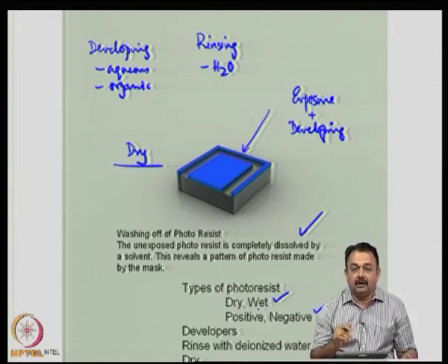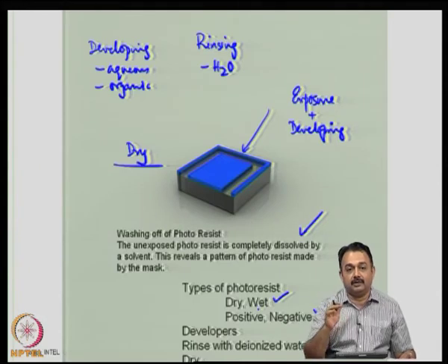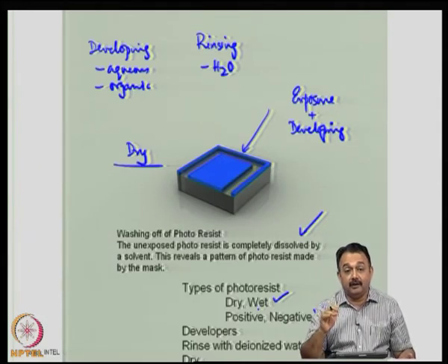When to use a positive mask and when to use a negative mask depends on what kind of image area of the circuit you need to have on the surface of the wafer. It can be the first step or the nth layer. So, depending upon the interconnection pattern and depending upon the availability of certain chemicals and equipment, you have to carefully choose the photoresist type.